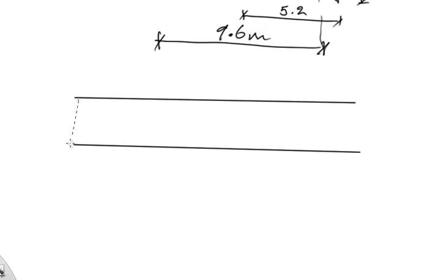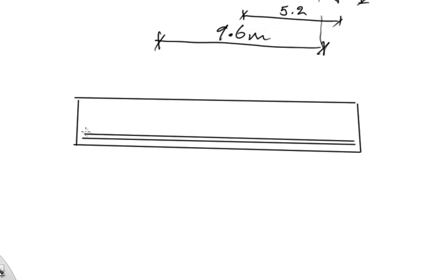I'm looking at the beam sideways, okay, and I'm having some rebars reinforcement at the bottom, and the reason we put the reinforcement at the bottom is the tension side is here, because you know, guys, concrete is good in taking compression, but it's weak in tension. That's why we add reinforcement in the first place.